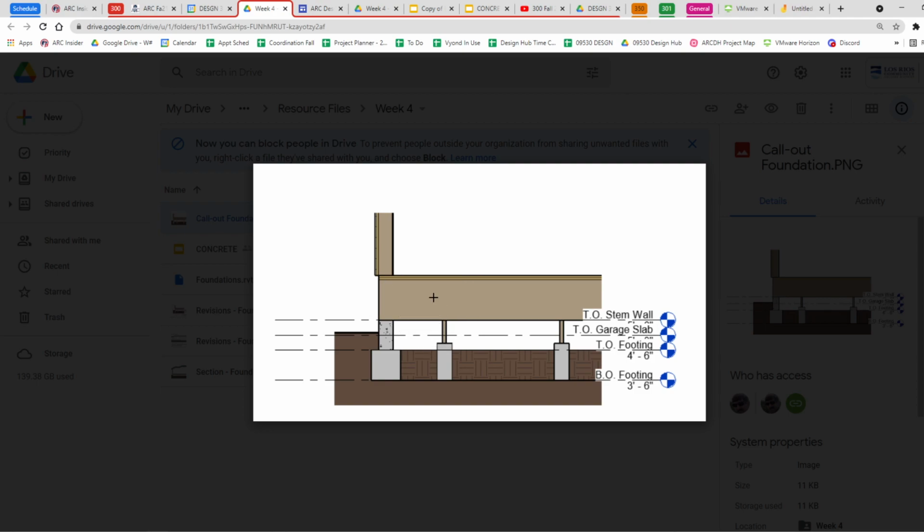This is some sort of wood system with a layer of some sort of sheathing and another layer of the sheathing, and the wall sits right on top of that. And there's probably anchor bolts, and it doesn't really say how the sill is done or how this is connected. It could be through anchor bolts or plates or something. So there would be a detail about that. And look, this is showing that there's some sort of siding that comes right down to that floor system. And tell you the truth, I would suspect that this overlaps by 3 or 4 inches.